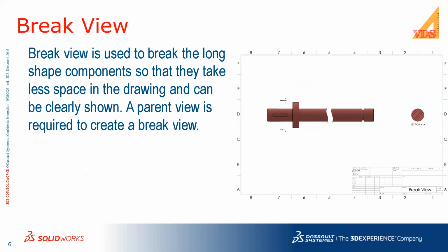drawing, because of their length, either the detail will be too small, or if we increase the scale so that the details on the view geometry are clearly visible, the view may go out of the sheet boundary. We want to show the detailed geometry of the model as well, and we want to restrain the view boundary within the sheet boundary. So we break the view, but we have to make sure that when we break the view, we are not breaking away any detail.